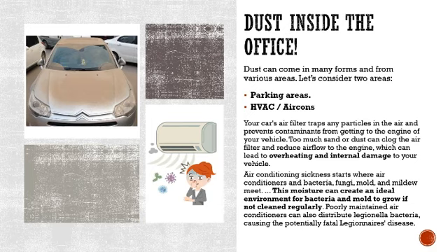Now, inside a vehicle, the filters will trap any particles in the air, and they prevent contaminants from getting into the engine of the vehicle. But if we do not have correct maintenance and we are not cleaning and checking these filters, then too much sand or dust can clog that air filter and reduce the airflow to the engine.